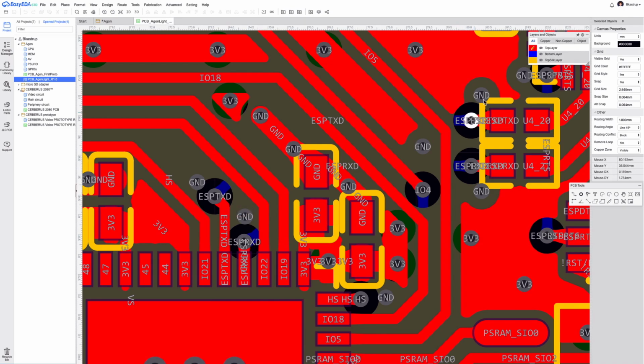Now notice that there are two ground vias right next to these two signal vias here, and here as well, a ground via right next to this one, and a ground via right next to this one. Now you will see this across the board. For all signals, I put a ground via as close to it as the design rules will allow me to do. And these vias, sometimes they are called return path vias or transfer vias. These are two slightly different things, but in this case they are playing both roles.